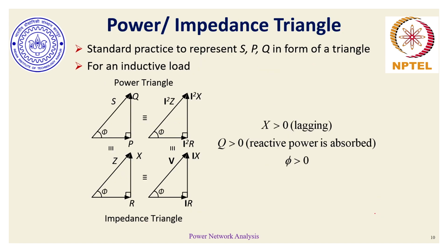If we have to represent these phasors on an impedance triangle or on a phasor diagram, then for an inductive load which has a non-zero R and a non-zero X, the corresponding current will lag the corresponding voltage across this RL element or RX element, which we can also correlate with the impedance triangle. And since voltage is nothing but current into the complex impedance of the element, we can also associate this in terms of voltage drops, from where we can also get the corresponding power angles.